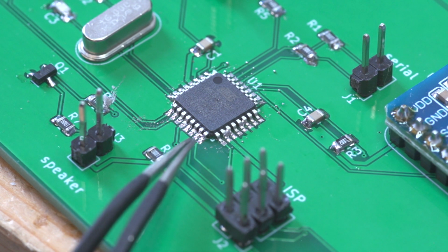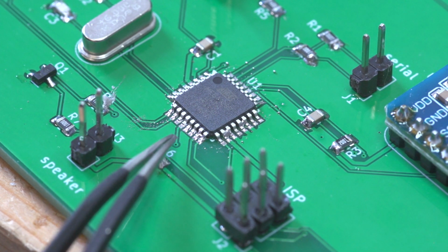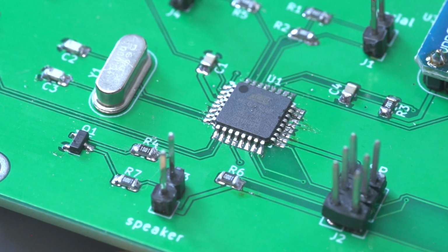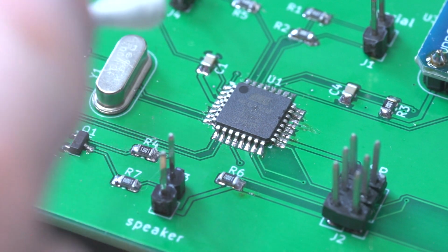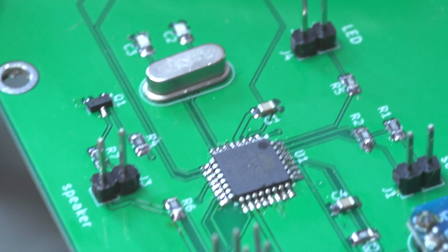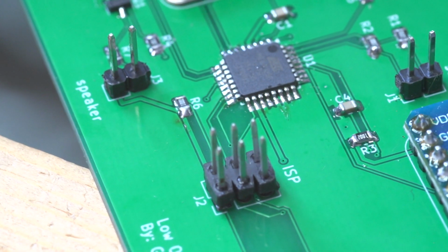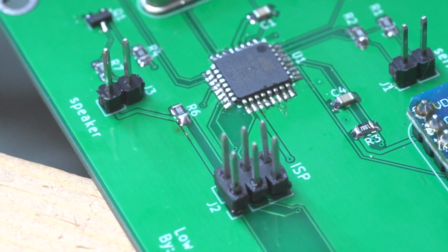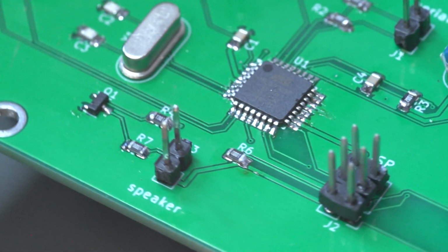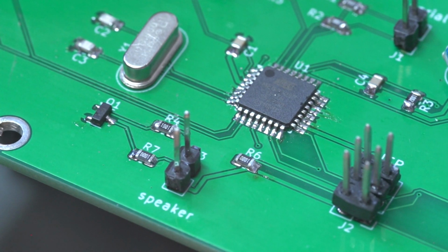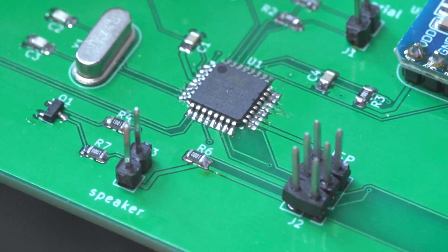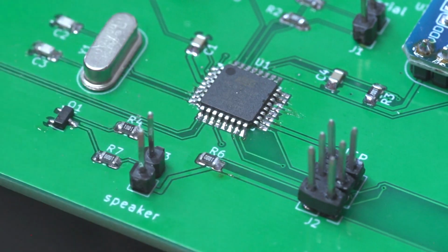I think I might have actually one here. Get a little bit of solder braid on there and just clean it up. Yeah, so I've just had a bit of an eyeball round the pins, gone all the way around, and had to touch up a couple. There was a couple of bridges, about 2 of them, and a little bit of solder braid or solder wick cleaned it up straight away, and that was it. So I'm happy with that now.